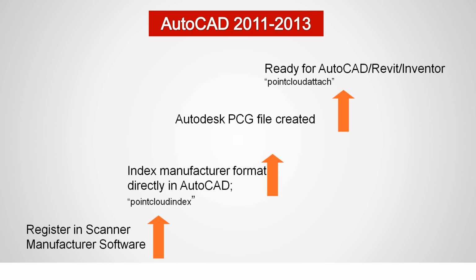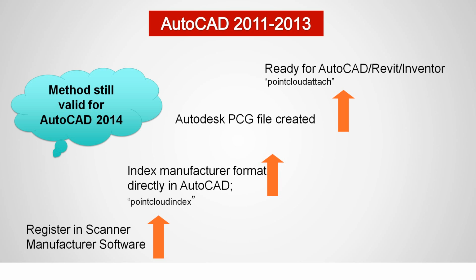And this PCG file you could then attach into any drawing. You could also type point cloud attach or just use the attach command inside of the insert ribbon as well. Now, this direct creation inside of AutoCAD still worked inside of AutoCAD 2014. So for those of you that are using 2014, you will notice that you can still create AutoCAD point clouds directly within the AutoCAD environment.